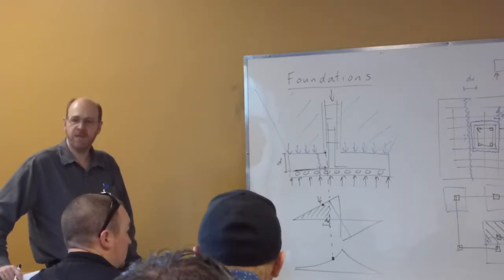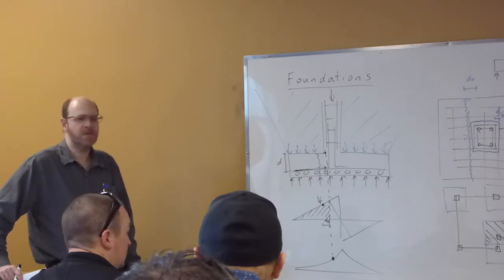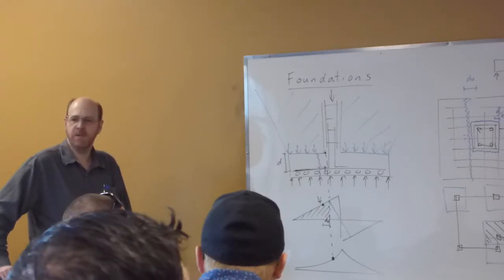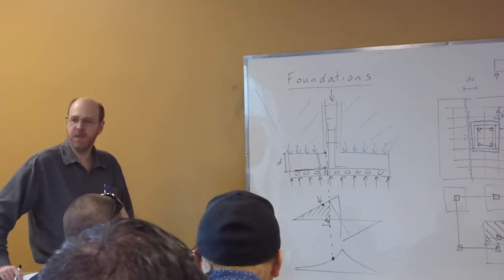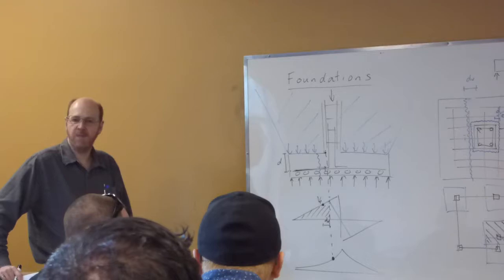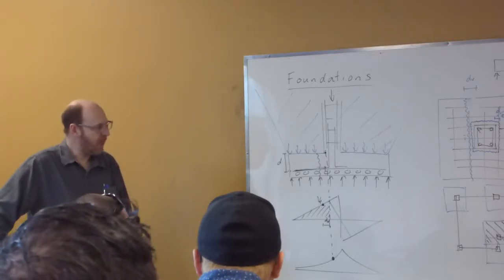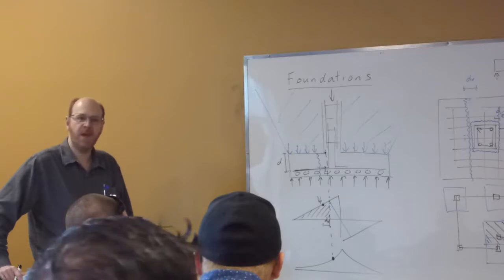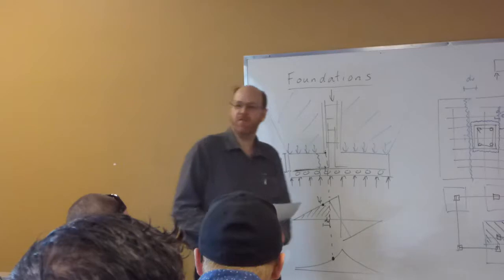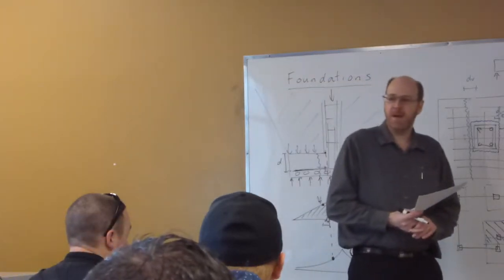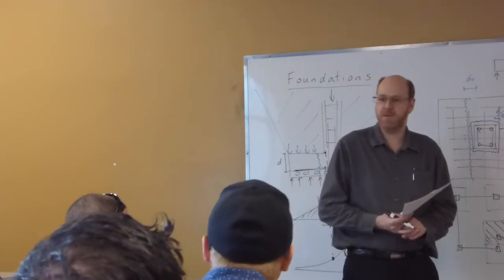So again, a fairly large volume of concrete. Now we also adjust things like our cover distance on here. Cover distance, remember, for a slab went down as low as 20 millimeters. It could be up around 40 millimeters for a beam, typically 40 to 60 depending upon the kind of environment you're in. But here with a foundation, it's quite common to have cover distances, and code specifies 75 millimeters as a minimum, but you can actually have more like 100 millimeter cover distance.